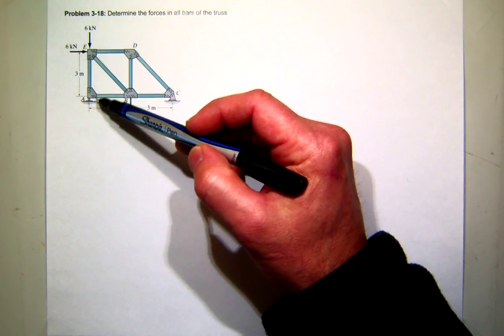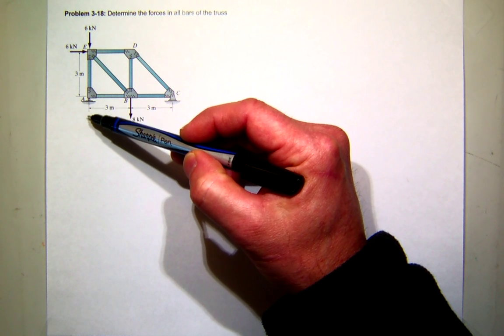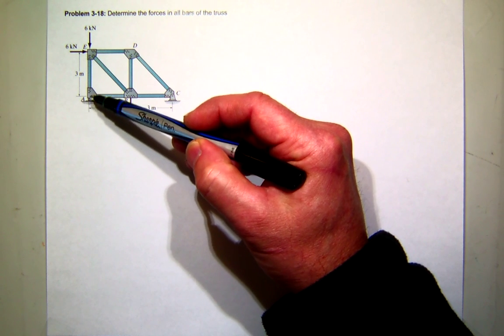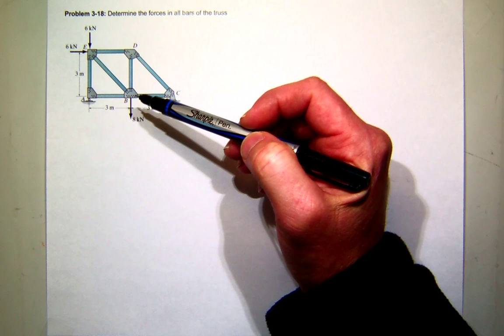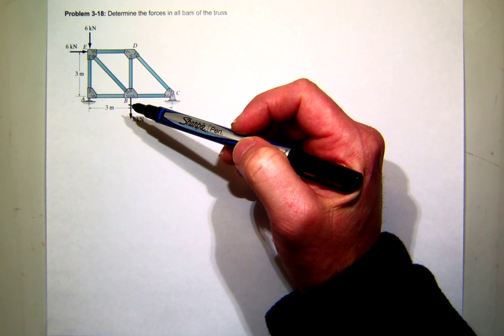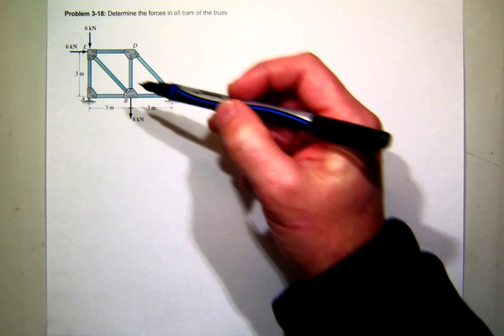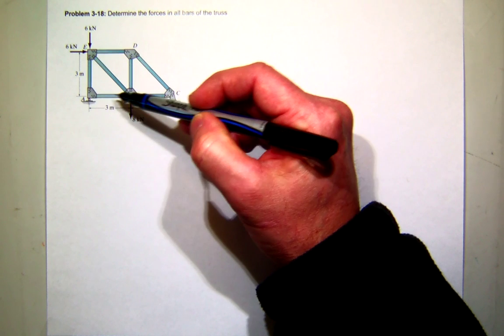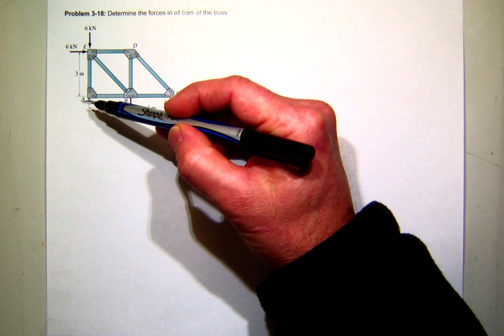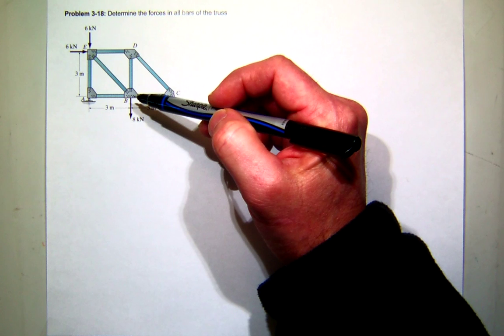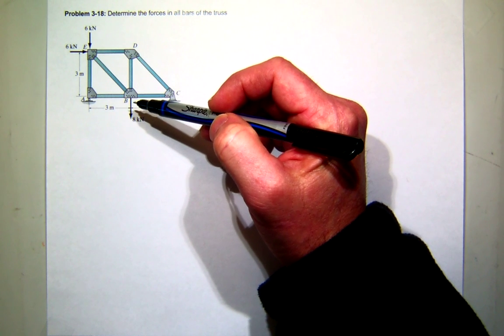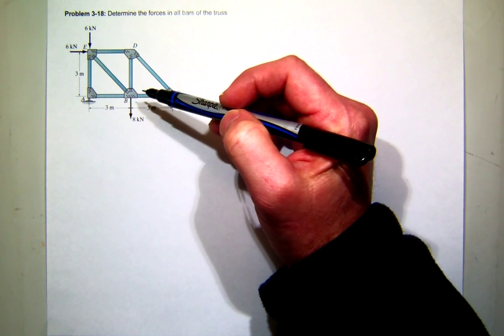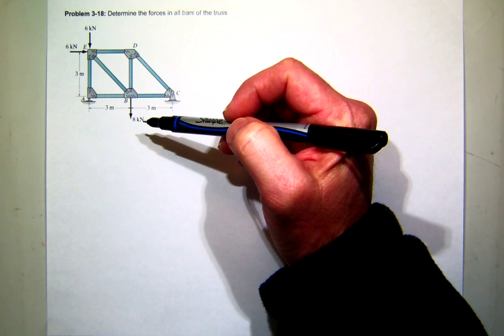When we do method of joints at A, you'll find there's only an AY reaction, so you'll find probably that AB is going to be 0. But that's harder to do by inspection, because with the multiple cases we do have 2 elements connected together, but there is a load. So by definition, they're both not 0. But in this particular case, AB will probably be 0. That's a good observation.